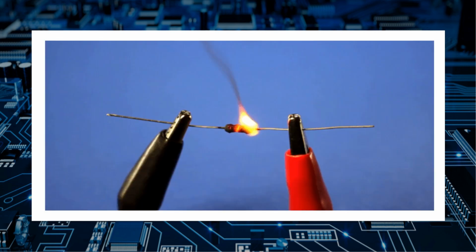Don't ever forget about power handling. Power resistors are large so they can withstand heat. Resistors dissipate power in the form of heat, and it's important to understand the power that the resistor needs to dissipate in your application. A resistor that's power rated too low for your application can lead to disaster and even cause a fire.